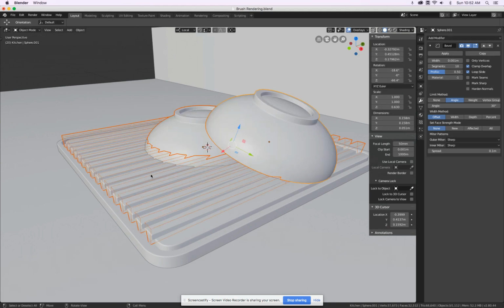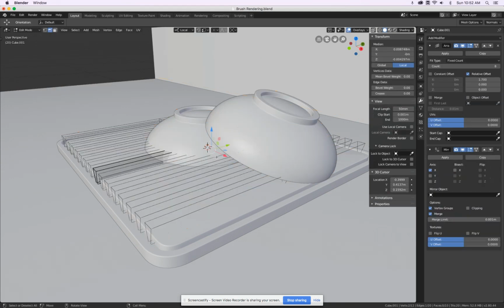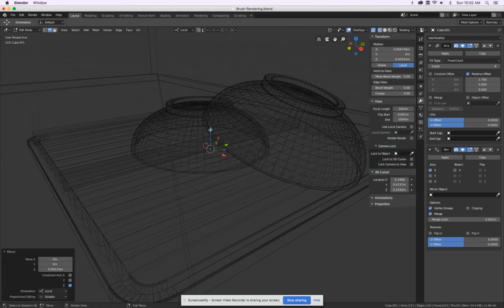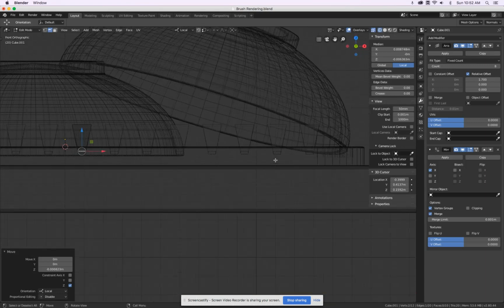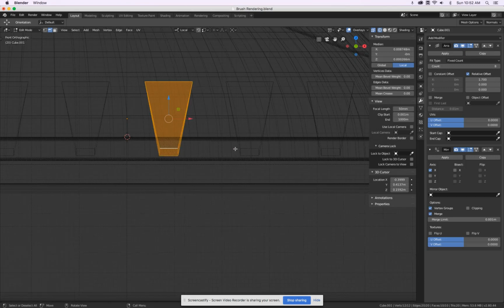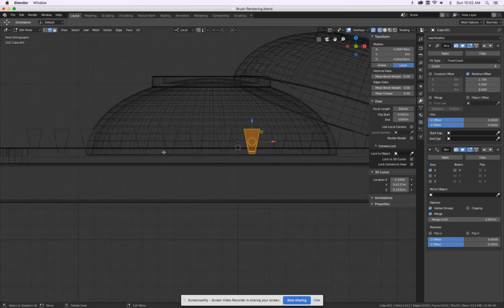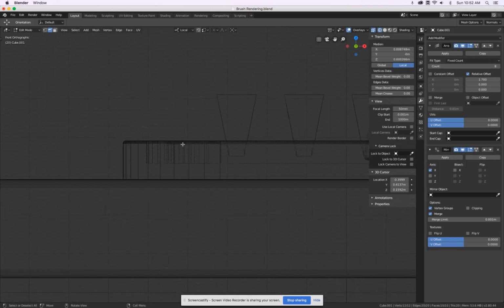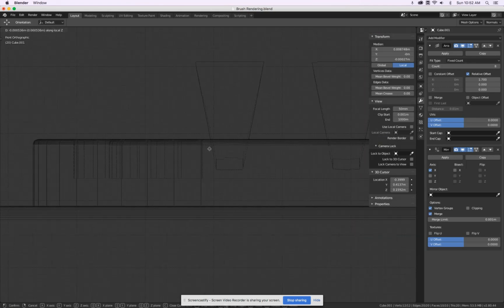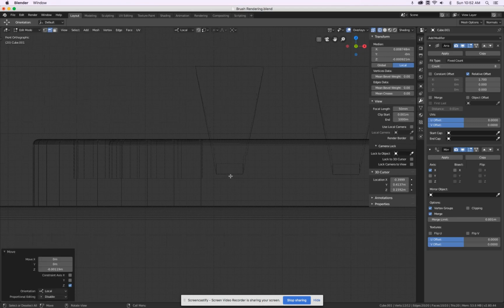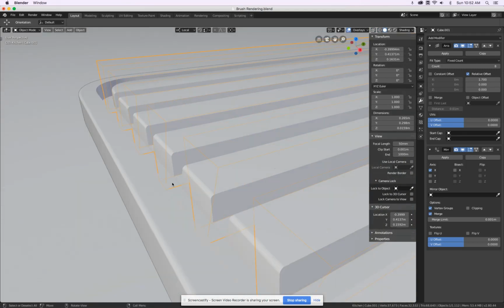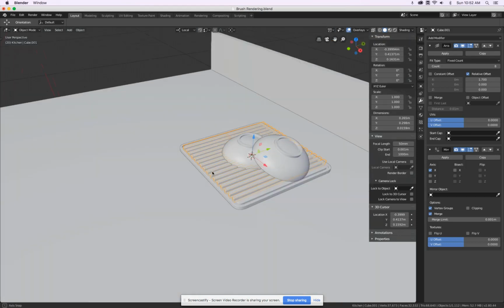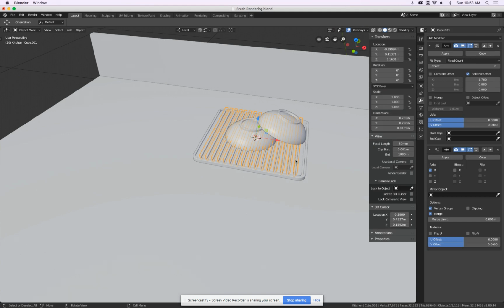So I just undo my height step, select this geometry, and maybe at this point down a little bit there. And I could select everything and then G and Z, move it, tick down. It's close actually to the bottom. As you can see, there's a small gap. Yeah, see, there it is. So we very quickly prototyped a nice detail too.